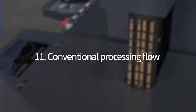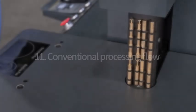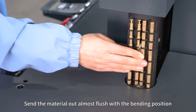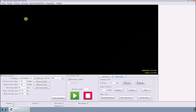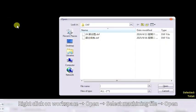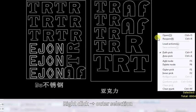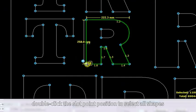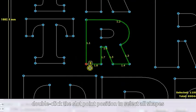11. Conventional processing flow. Send the material out almost flush with the bending position. Right-click on Workspace. Open. Select Machining File. Open. Right-click. Outer Selection. Slide the mouse wheel to zoom in and out of the graphic. When picking up shapes, double-click the slot point position to select all shapes.